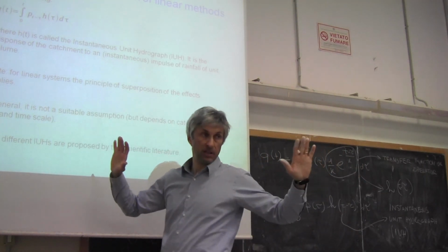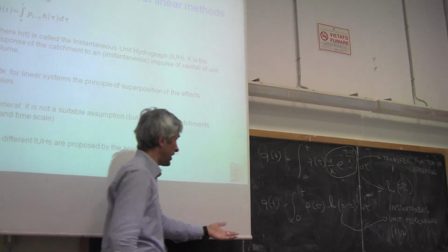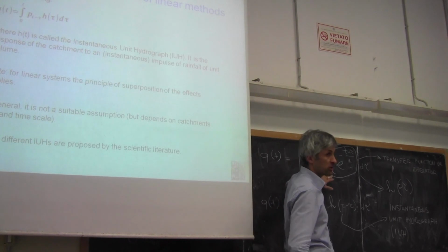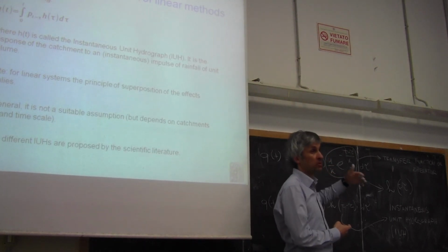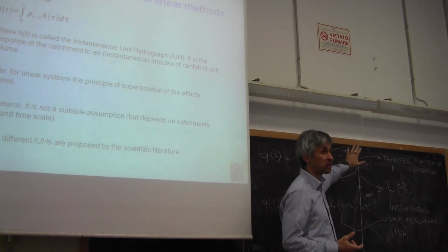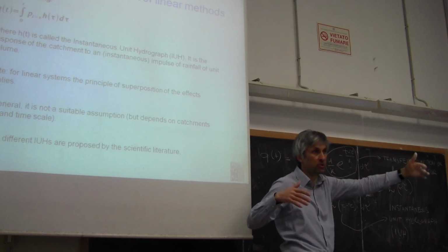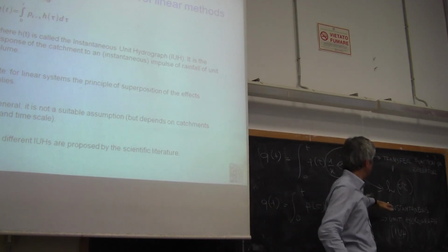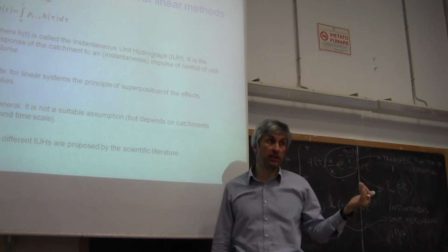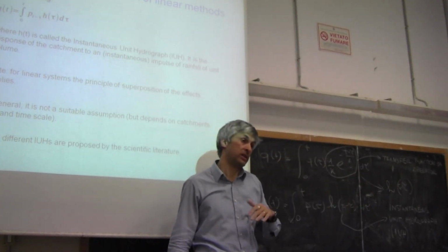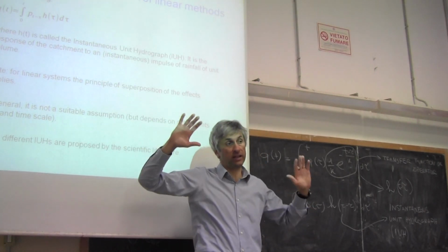That's it. For the linear reservoir you have for H the expression that you see here. For the time area method, it can be proved that there is another relationship for H. For any given linear model, you may find a relationship giving the value of H depending on time. And as I said, this compact form is valid for any linear model.